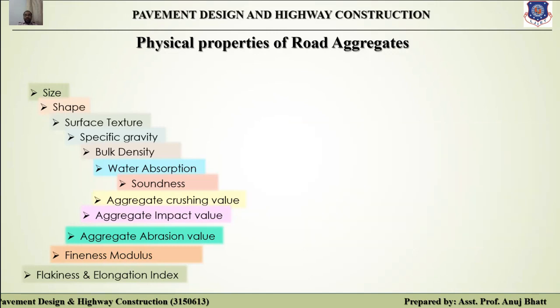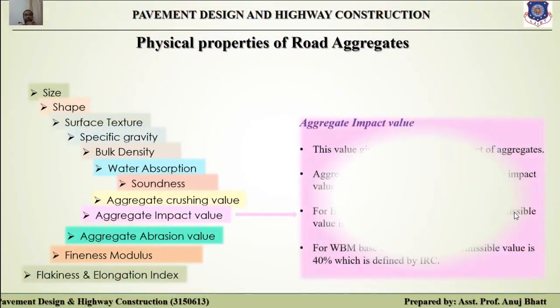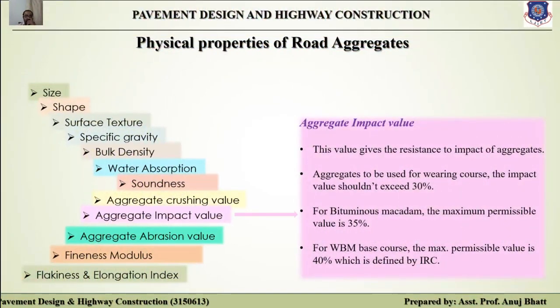The next is aggregate impact value. Now, the impact value test is to determine the relative measure of resistance of aggregate. Resistance of aggregate to what? To the sudden shock or the sudden impact, in which some aggregates differ from their resistance to a slowly applied compressive load.